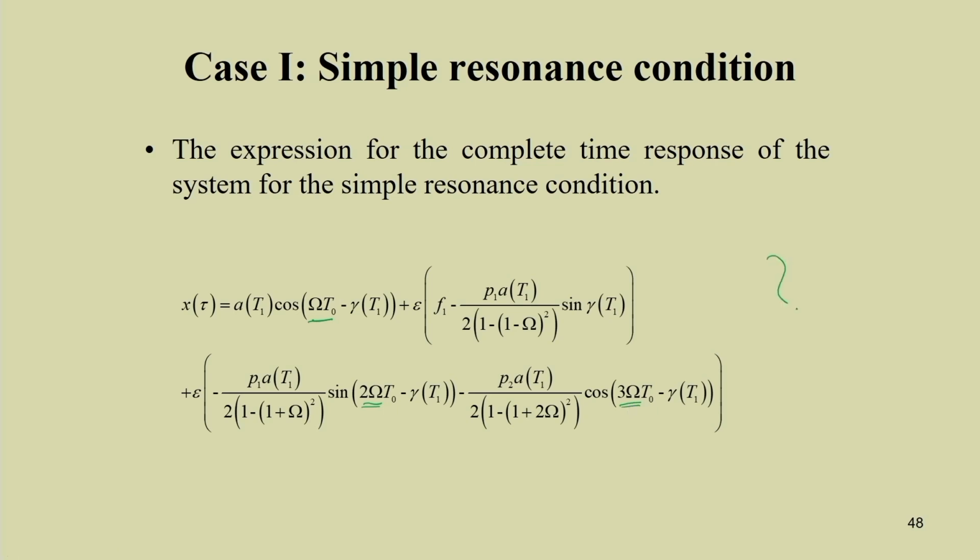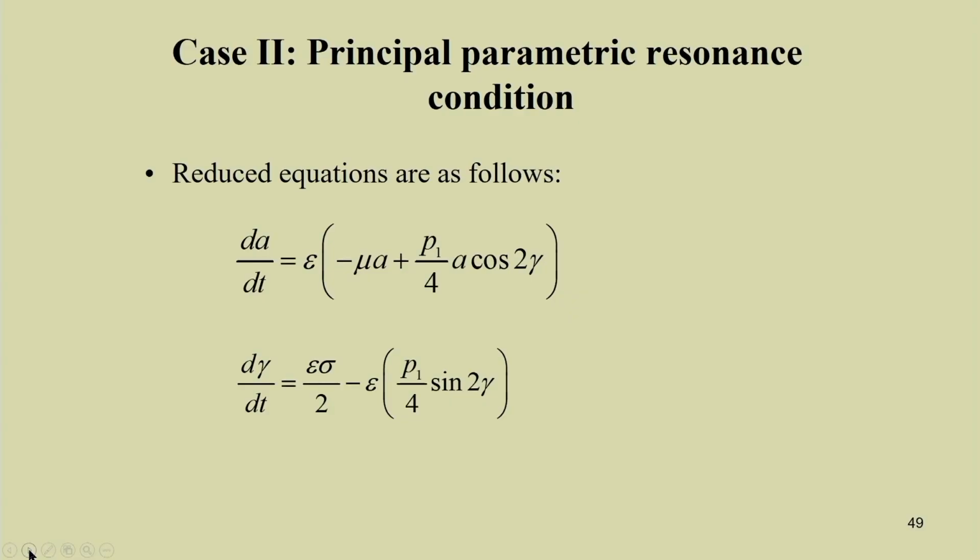So, this way you can find the response of the system, and by plotting this response you can check the response of a pneumatic artificial muscle. This artificial muscle is a function of the muscle parameters, which are written in terms of F1, F2, F3, that is C1, C2, C3, D1, D2, and also the pressure. By changing this pressure, you can actively control the motion of the actuator. So, this can be used as an actuator, and you can control the motion by actively changing this pressure.